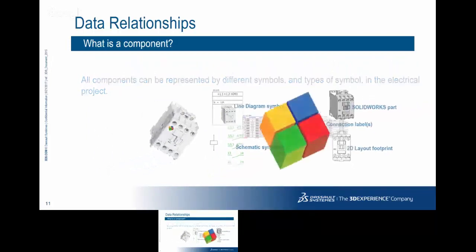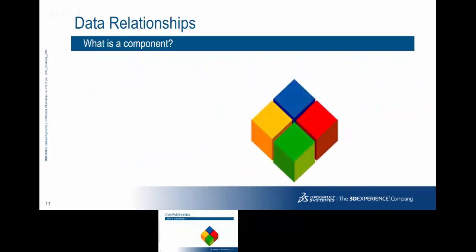All of those are under that master component. That's why, when I went into the library, there's a symbols manager and a manufacturer parts manager, because I can have symbols associated to a component and no manufacturer parts if I don't know. Think of your manufacturer part as what you go to the catalog to order.